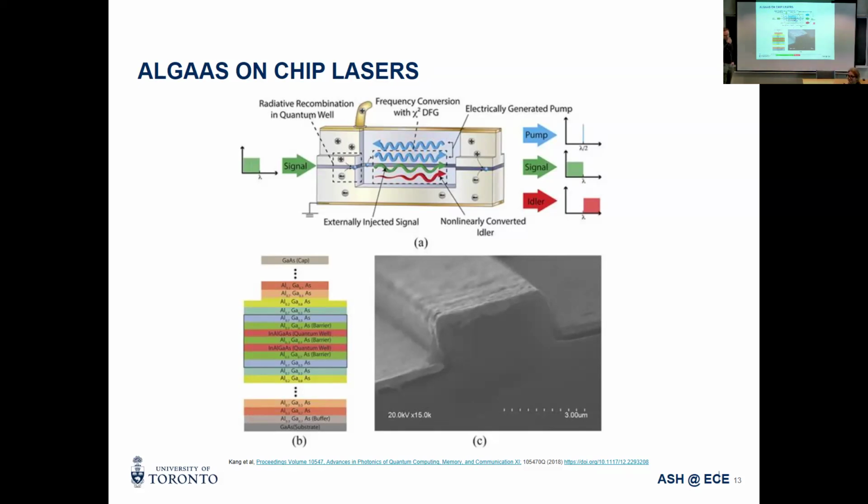Is there a benefit to smaller radius resonators besides scalability? Do you have less loss? No, usually when you decrease the size of your resonator, you decrease the bending radius, and you actually end up increasing the loss. Besides scalability, there isn't.